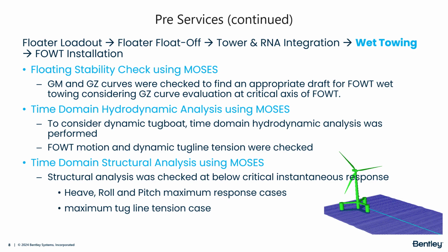Time domain simulation was also conducted to analyze the dynamic tensions in the towing lines caused by the tugboat. Dynamic tension refers to nonlinear behavior, such as when a slack line suddenly becomes taut, potentially generating extremely high tensions. These effects were captured during the simulation.